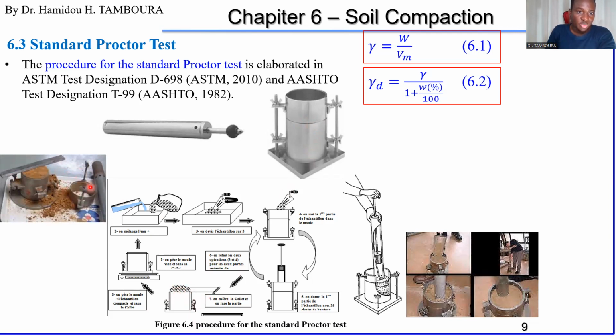See, you take off the extension, this part, and you use this tool to remove any excess soil here, because we want it to be very flat so that the volume will be respected.